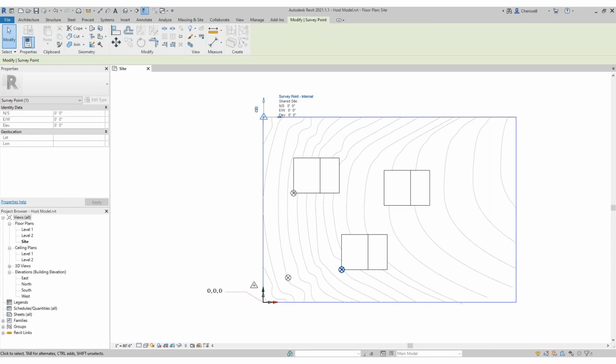And you can move it back closer to the origin point, so the model does not exceed that 10 miles radius limit. And honestly, I felt that it should be 000 because I don't want to have people straining to try and notice the difference once this is clipped and moved. You see that the coordinates stay the same. It's 000, but I can move it in closer. So every time you do a zoom all, you're not zooming way out.